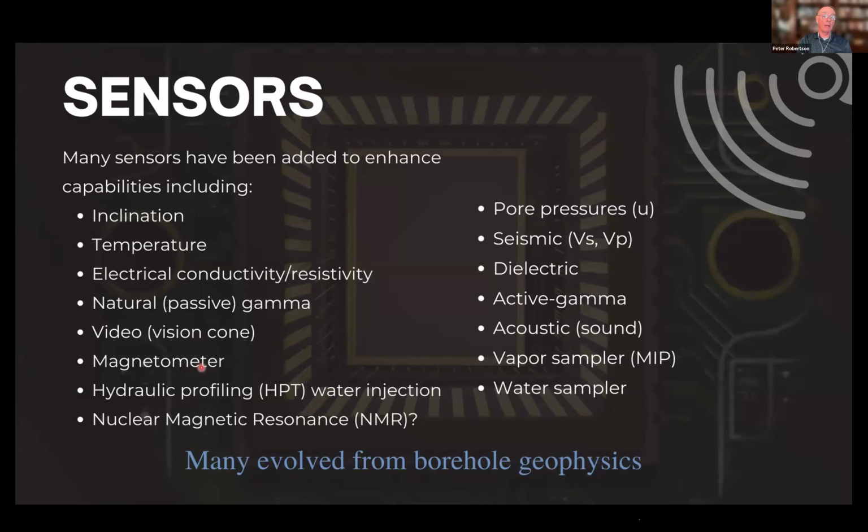In Europe, magnetometers have been added to detect metal. And in fact, surprisingly, in Europe, it's now quite common to use the cone with a magnetometer to detect unexploded bombs from World War II. So you push rather slowly, and you detect if you're approaching something that has a lot of metal in it. And of course, if it detects that, you stop, and then you determine that there's something with a lot of metal there, and it could be a buried bomb.